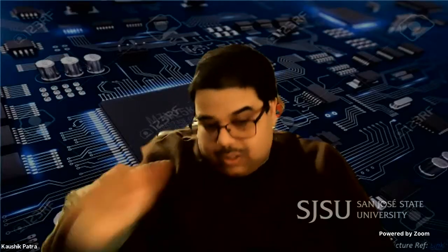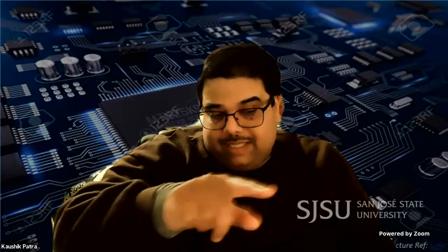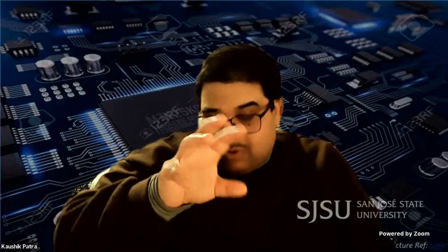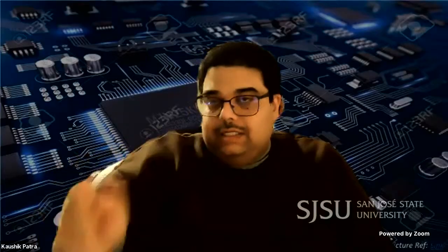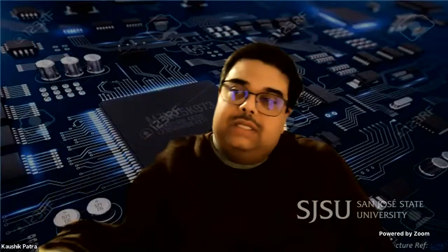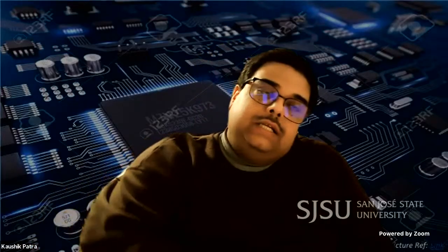One digital value to the BCD code. So basically it says your problem space is from digit 0 to 9. Digit 0 to 9 convert into the, sorry, it's not BCD, it is the XS3 example. So each digit is represented as a +3 value. That means 0 is represented as 3, 1 is represented as 4, 9 is represented as 12, that bit combination.